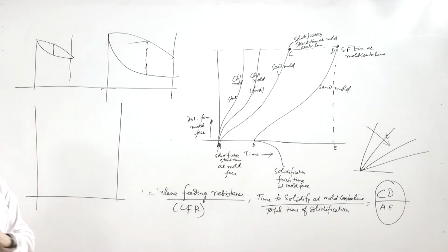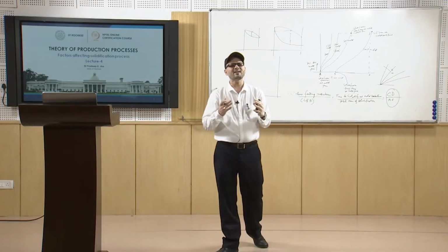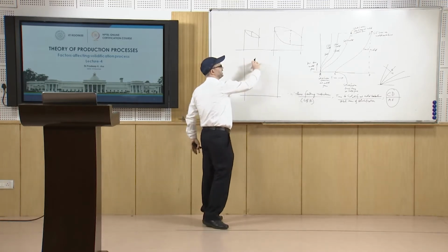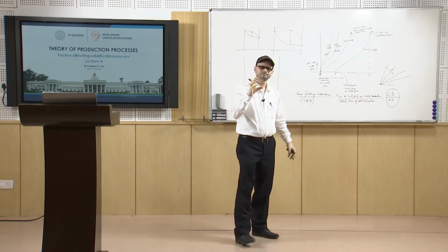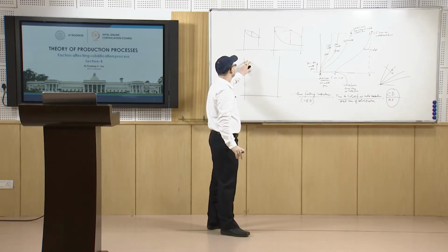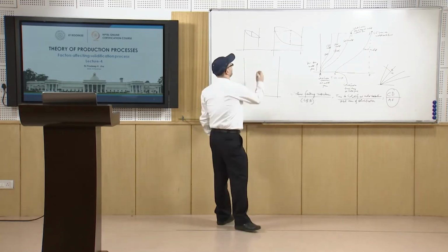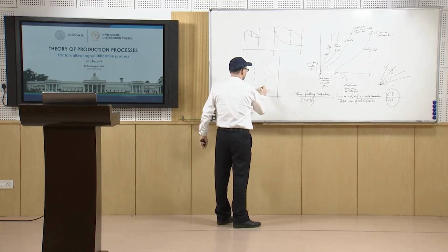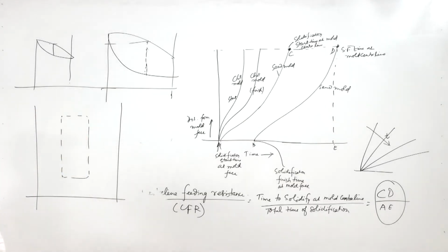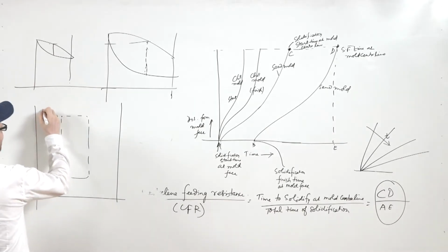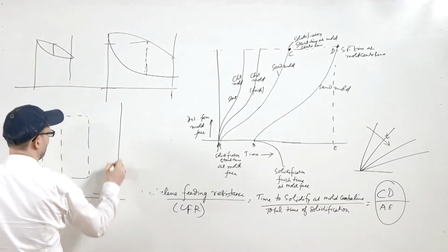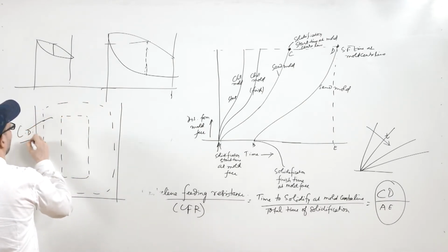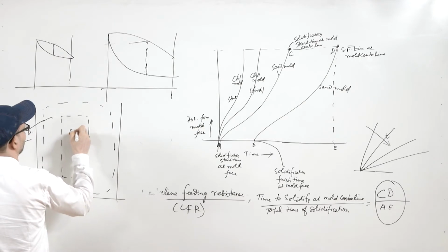Solidification starts at the walls, and then you will have the formation of columnar dendritic grains near the walls, which start growing, and then in the central portion you will have the formation of equiaxed dendritic grains. So, in this zone you have a columnar dendritic structure, and here you have equiaxed dendritic structures.